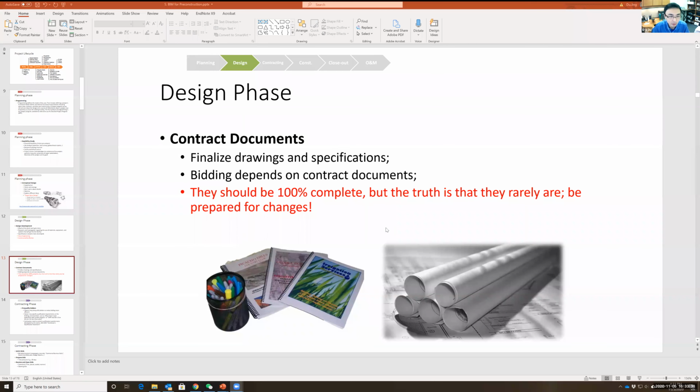Fabrication, yes, correct. So if you have some steel columns and steel beams, and you need to send them to a shop to punch holes and create a certain size of screws, and you have to show that clearly in a drawing, that's called a shop drawing. It's extremely time consuming to produce that information. Okay, so that's how the specification and drawings look. So who produced these documents? The designer.